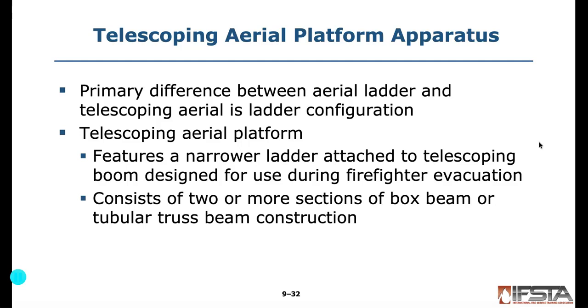A telescoping aerial platform apparatus. The primary difference between aerial and telescoping ladder is the configuration. The telescoping features a narrower ladder attached to a telescoping boom designed for use during firefighter evacuation. It consists of 2 or more sections of box beam or tubular truss beam construction.